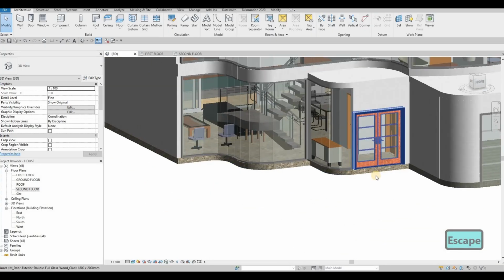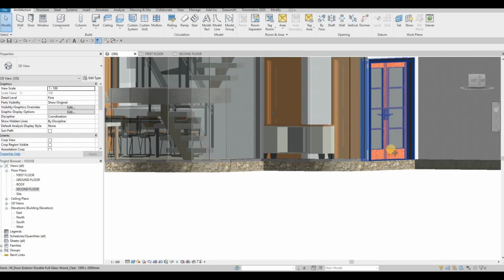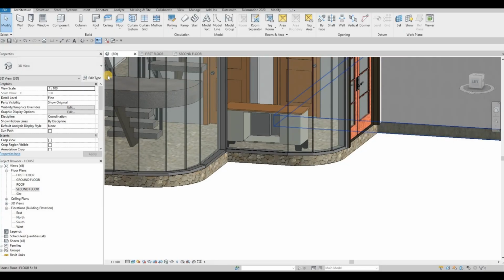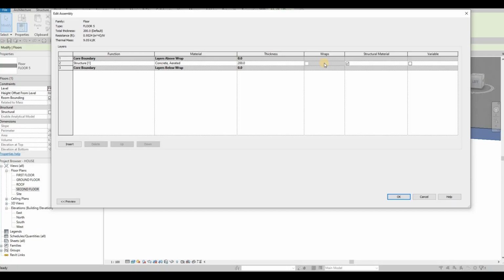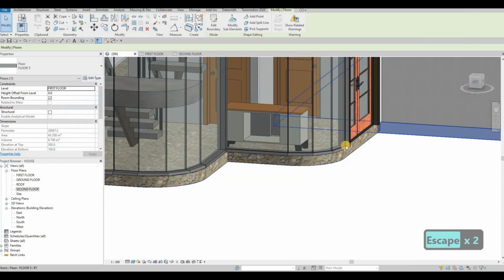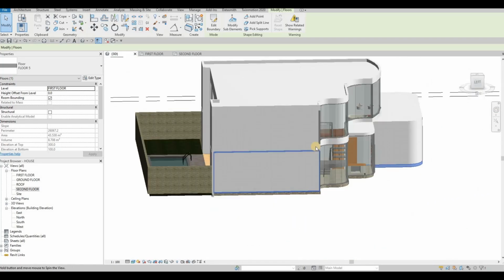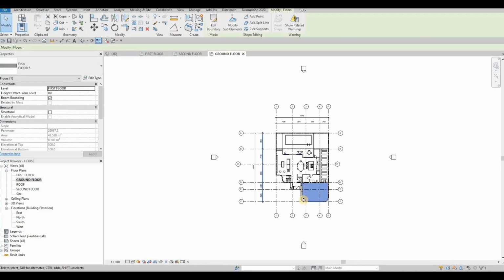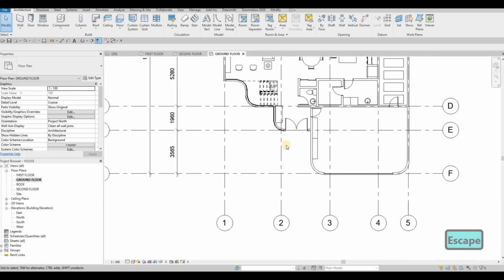And then next I want to add in the stairs here. So I believe, because this one is 200, actually we don't need stairs anymore because this is ground already, so we don't need stairs here. Everything is grounded. So what I'm gonna do is go to ground floor, and then I'm just gonna set my grass area and then my walkway here.